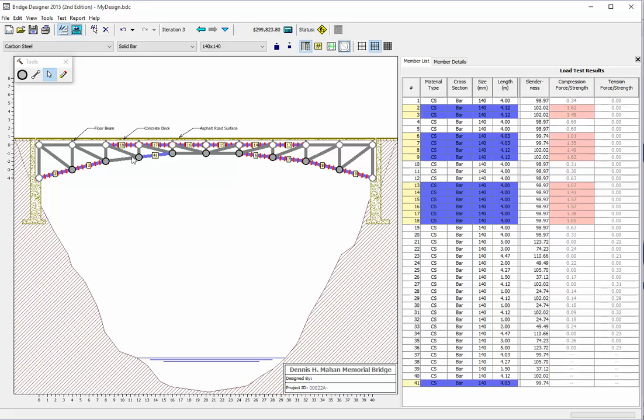In fact, I'll do these two as well since I think I deleted them earlier. When we click on all these red dashed lines, we've selected them. So let's now go to this drop-down menu that says carbon steel, and we're going to change this to quenched and tempered steel.